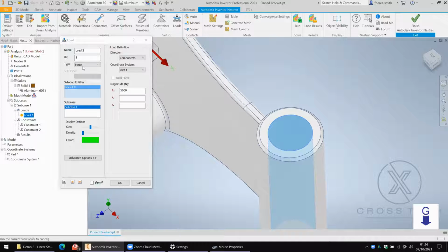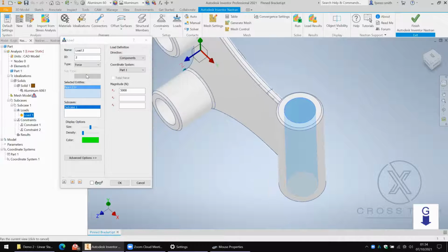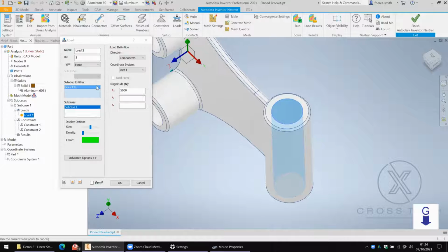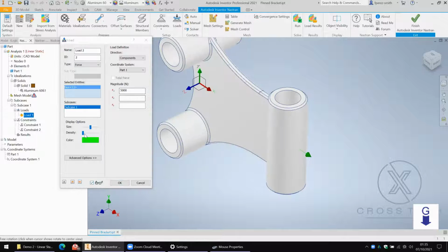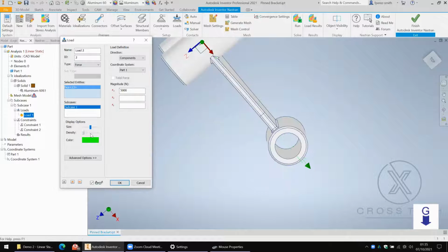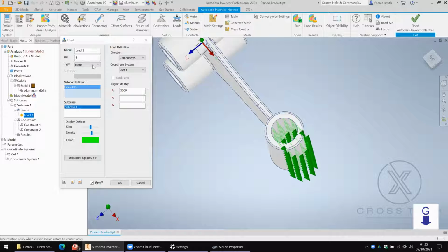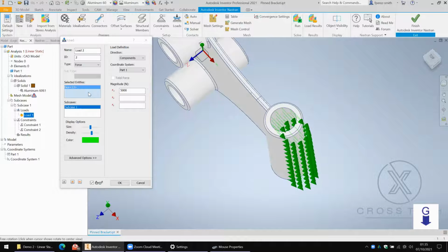But in this case, it's going to be a pole that's stuck in there applying a bearing load. So we'll have a look, using this little icon, at what those loads look like. I'll just increase the density of these arrow vectors. And as we can see, by default, it's applying the load uniformly on that surface. Now, what we want to do is change it to bearing load.